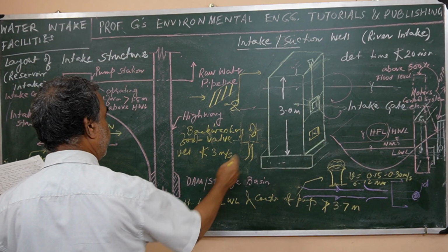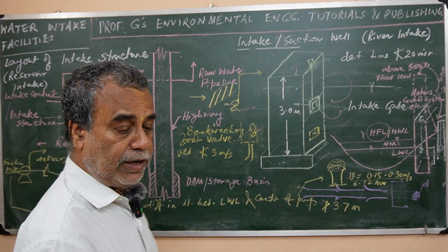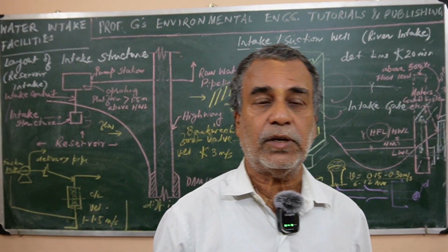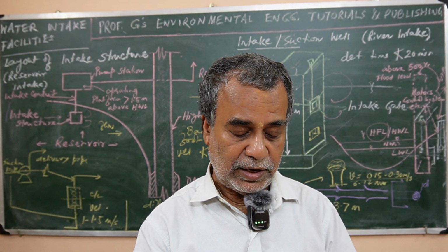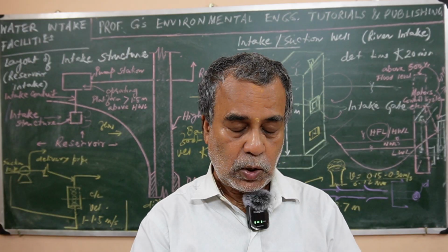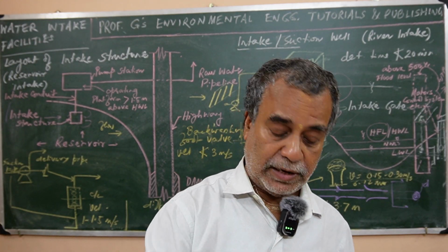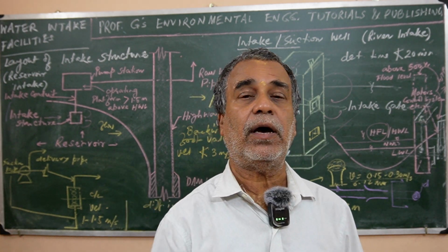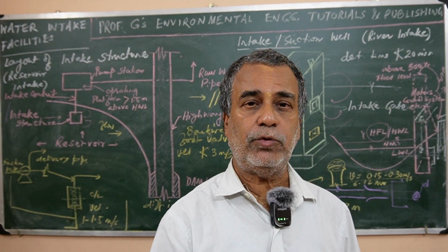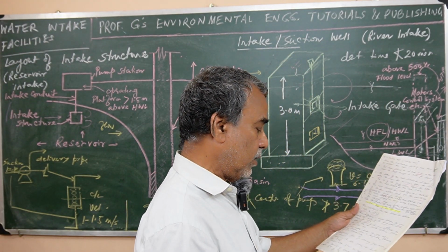Treated water shall be used for cleaning. If the cleaning water itself contains unwanted materials, then they will remain even after cleaning. That is why the treated water, which is free from these substances, must be used while cleaning the foot valve through the backwashing pipe.